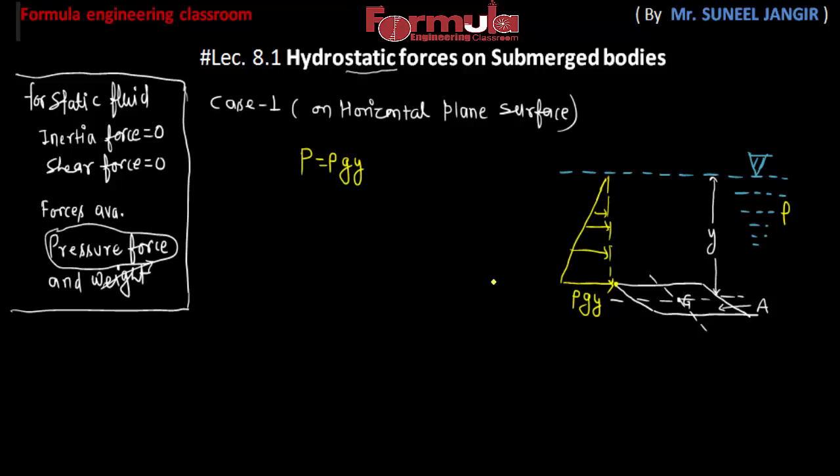Now according to Pascal's law, in a static fluid the pressure intensity at a point remains the same in all directions. So the pressure intensity in this direction and in this direction at this point will be the same. And this is a horizontal plane surface, so every point on this surface has the same depth from the free surface.